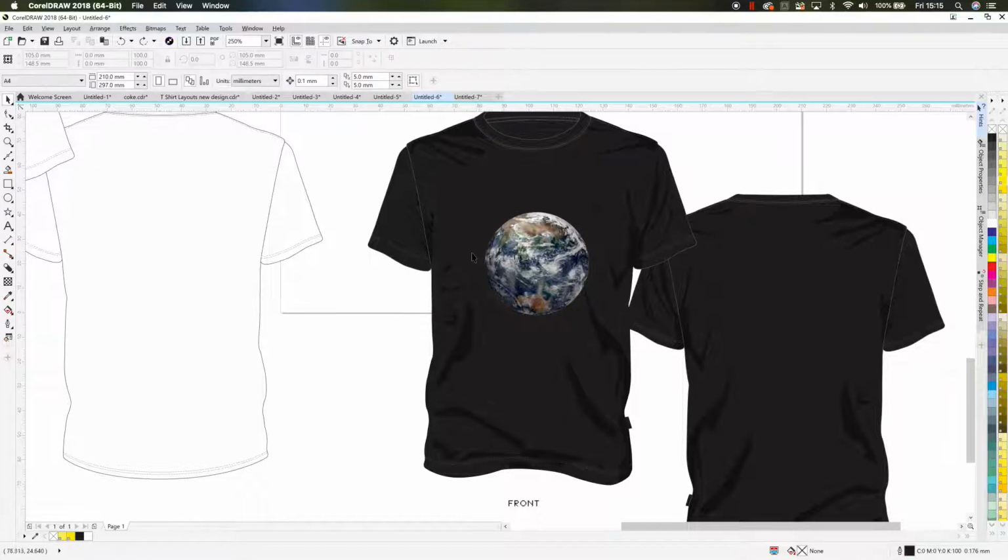You print your transfer to a paper, and then you also have a white ink carrier paper. You heat press the 2 components together, your transfer paper and your white carrier paper, and you release it almost immediately under heat.